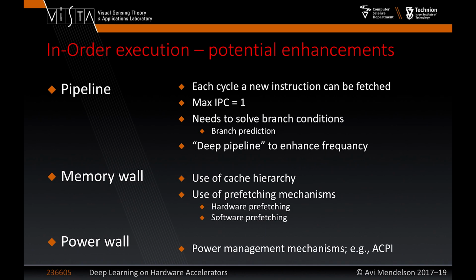At Intel, a long time ago, there was an architecture called P4 or Nehalem. No, what was the name? Tejas was one of the versions that they worked on. And in that architecture, actually, they had something like 50 pipeline stages. Why? Because they wanted to reach a very, very fast clock rate. It costs a lot of power. This is the reason that they stopped doing it. But in general, we can expedite the clock rate.